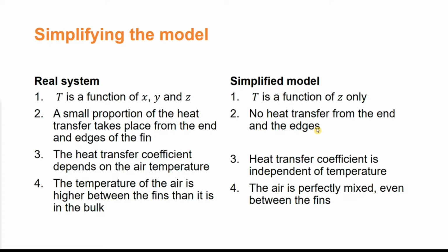The heat transfer coefficient depends on the conditions of the surrounding air. To simplify the model, we can take this to be a constant. In the real system, the air between the fins is likely to heat up, and we will need to account for the flow of air taking heat away from the fins. A good simplification is to assume that the air is at uniform temperature, unaffected by the heat coming from the fins. It is an infinite sink for the heat.